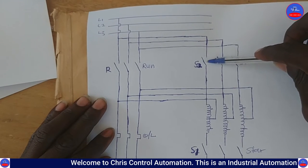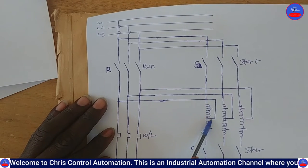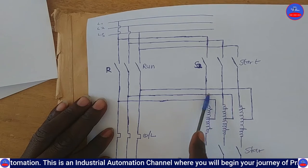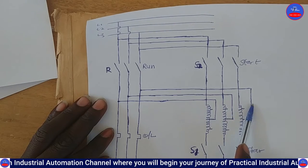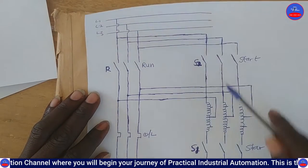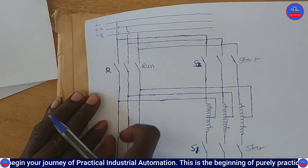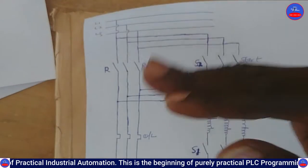Let's see here. You see it, and then it will go like this. You see this one too. You see, they are all in series. So it means that when this side opens whilst this side is closed, part of the winding, not the whole winding, from here to here, is going to be in series with the motor windings, acting as a choke or reactor, so that the motor will still maintain its speed.